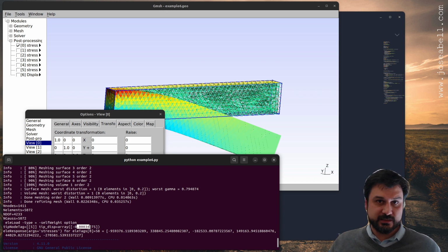The reason for that is that finite elements are always stiffer than the equation they're representing. So you're going to get a stiffer result than what you expect from the mathematical model that you have, right? As I increase the discretization, this should take more time, and this displacement should converge to a larger value.